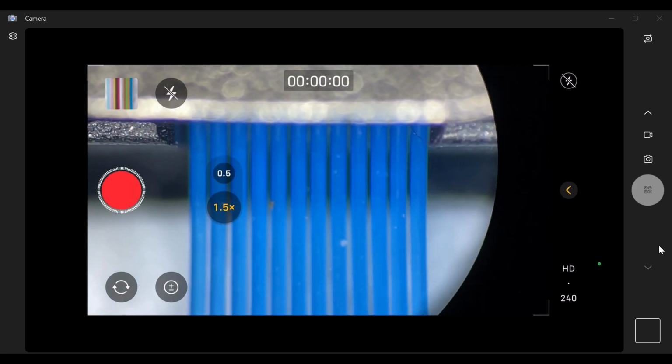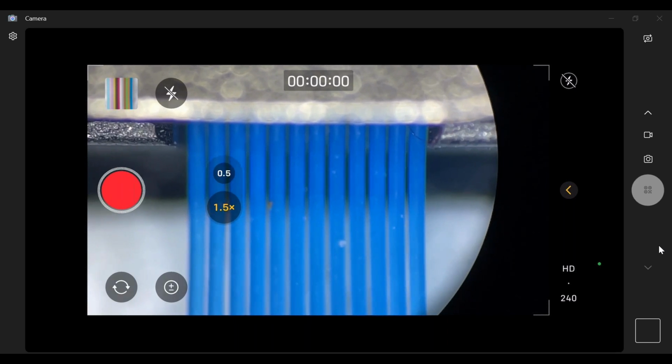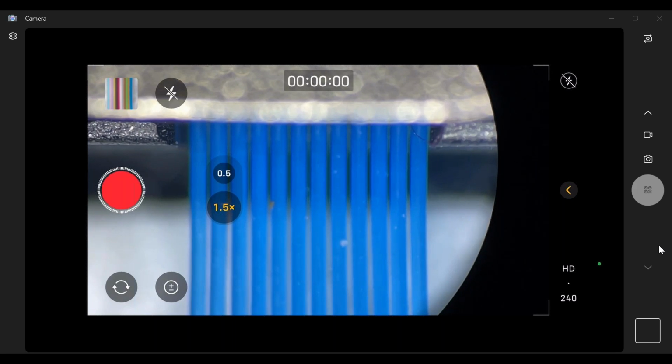So this is a 200 micron loose tube fiber that has been run through the ribbonizing tool and placed into the F870-12 PC fiber holder. Look how nicely these fibers are orientated, and the more precision you have of guiding that fiber to the back of the V groove of the fusion splicer head, the more success you will have as far as your splicing process.